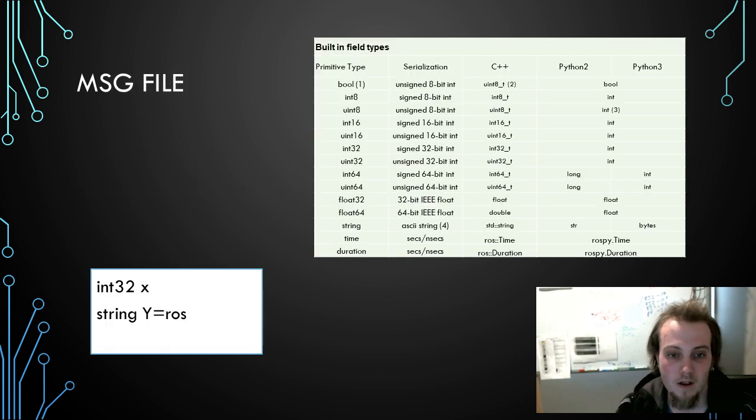The first message type we're going to look at is messages in the .msg format, and these are used for topics. A .msg can include fields to send data, and also include constants that can be used to interpret the data that is sent. Remember, topics only send data, okay? It's one-way communication. Each field needs a field type, and these types can be any of the inbuilt types that are shown here on the slides.